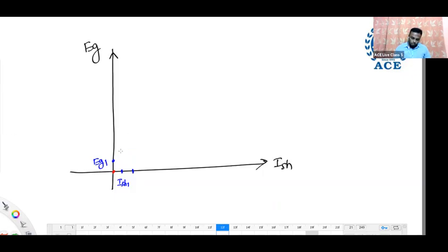The voltage builds up continuously. Up to what will it build continuously? Saturation. Assume that saturation takes place here. At this point saturation occurred, because the field current is continuously increasing. At one field current, the flux in the poles reaches a constant maximum after the saturation.